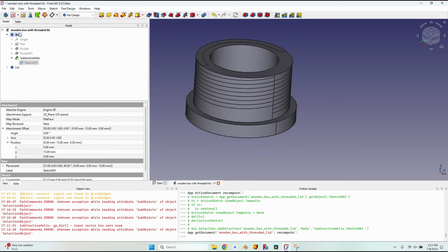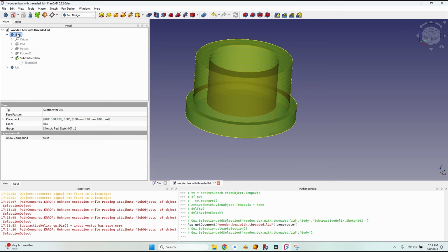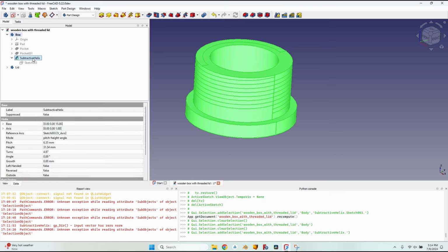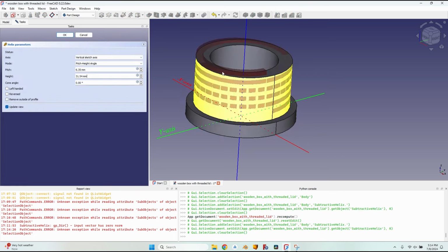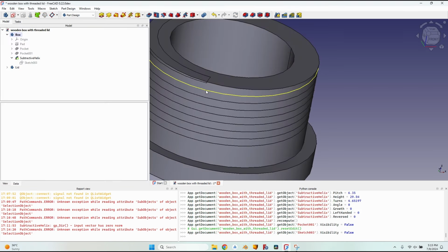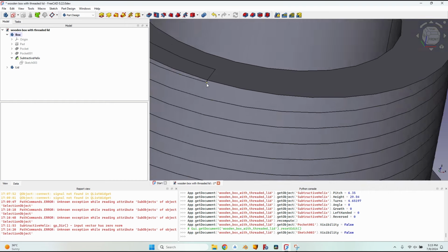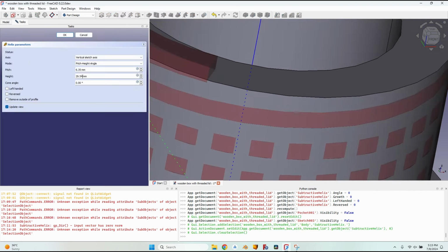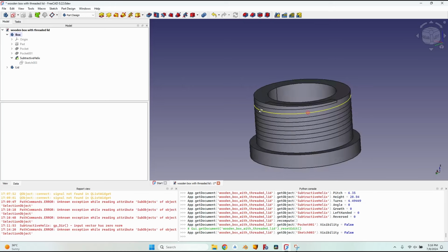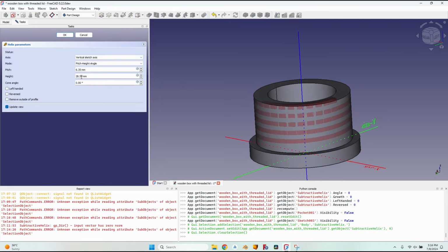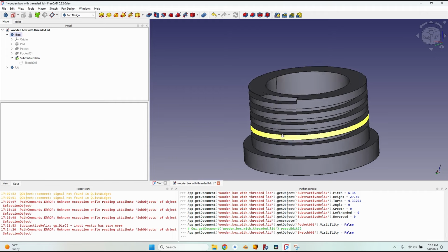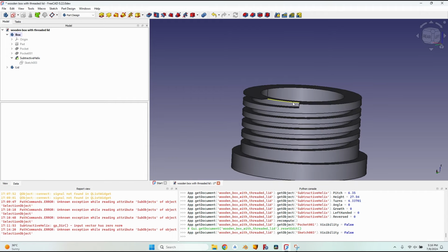This is the reason that even though I need a box of 35mm tall, I have created it with a height of 45. So I will go to the Subtractive Helix and I will reduce the height until it still remains a little bit in the material, but this little bit needs to be a little larger, so I'll write 28 here. 28 is still not enough, so I will double click again, reduce it to 27, and now the helix looks okay. I consider this a bug.